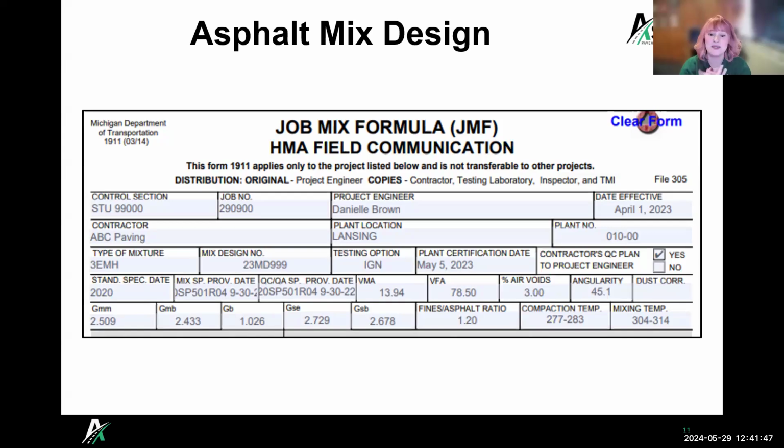That's all right. It's one of those like the little bit of water that's around the aggregates in concrete design, those kinds of things. Yeah. And then you've got to subtract out some stuff for absorption. The voids filled with asphalt is how much of that void space is being filled with asphalt, and that creates your paste, basically, of the liquid asphalt. And there are specs on those, usually it has to be above or below a certain point. Yeah, this is part of the volumetric testing, really. Gotcha. Make sure you're meeting that spec.